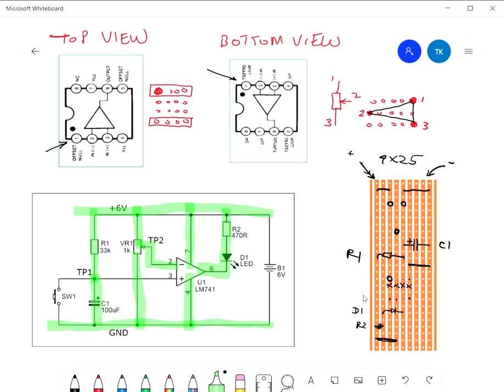So what do we do? We make a break or a cut in the copper. So I'll put a cut there, and X, to show I'm going to cut the copper there, so that now I've got this strip of copper here connected to the positive, and it is broken and it won't be connected to pin 1.